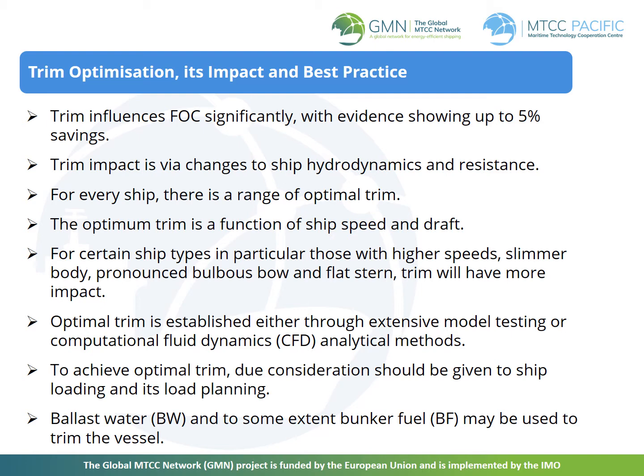In some ships, it is possible to assess optimum trim conditions for fuel efficiency continuously throughout the voyage. Setting the ship trim is to a large extent in the hands of the shipboard staff, although loading, operational, and navigational constraints may limit the proper use of this energy efficient measure.